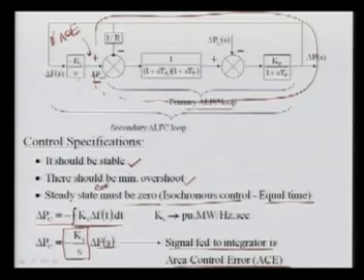I have already used this block here, and then we can have the secondary load frequency control loop. Then we will see whether this loop is stable and what the value of Ki will be. That is very, very critical, and it decides several things. This Ki value must be chosen to meet your requirement, and we will now see the static as well as the dynamic performance of this secondary loop, along with your primary LFC loops.